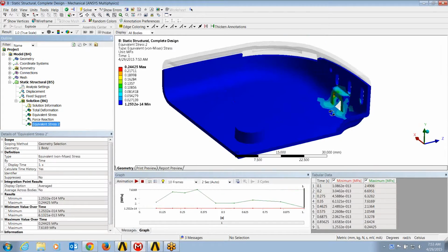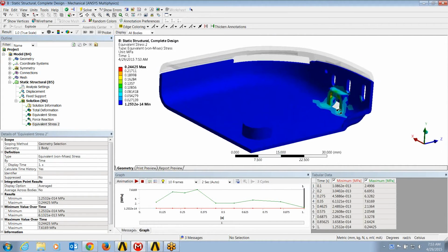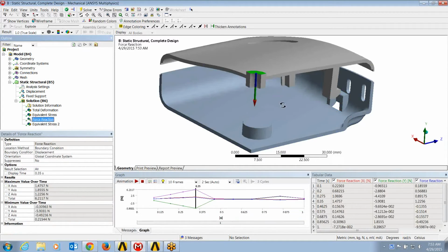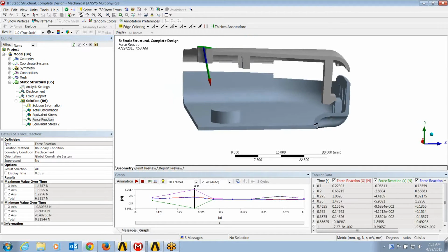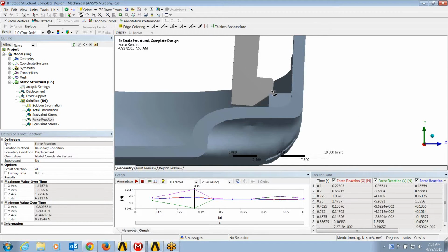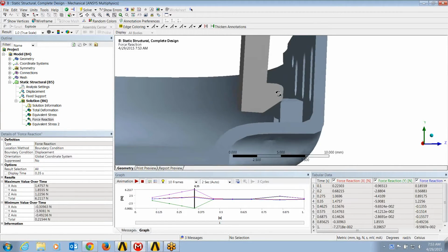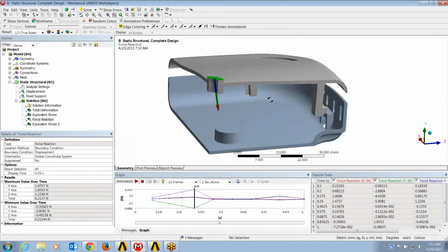We now have also information on what's happening in the bottom cover. We can validate that stress region there. And as we mentioned earlier, we can now retrieve that maximum force required to insert that top cover into the bottom cover. And we find that very early on in the assembly process, right as that beam is coming over that post, the edge of that post there, is when the maximum insertion force occurs, and it's about 6.2 newtons.